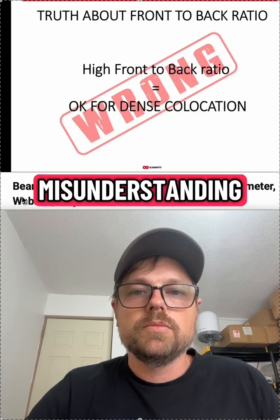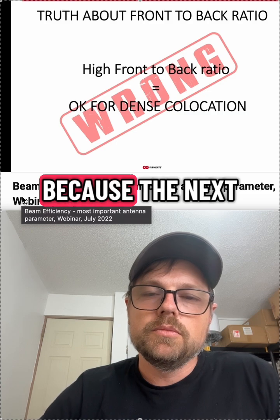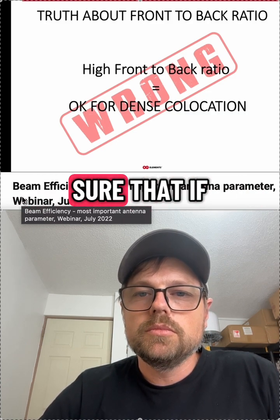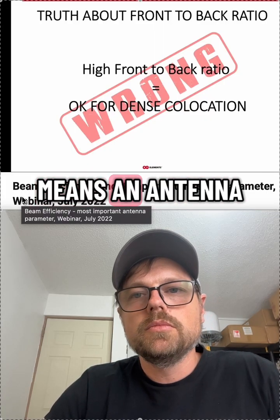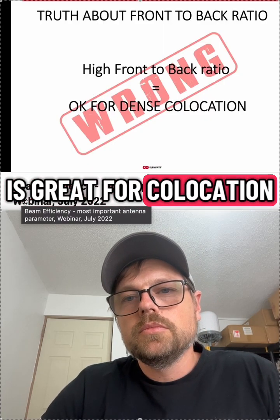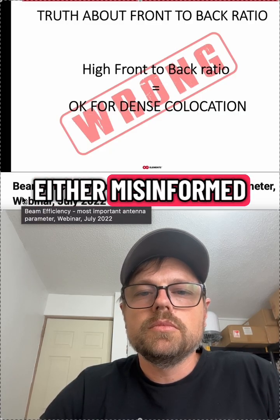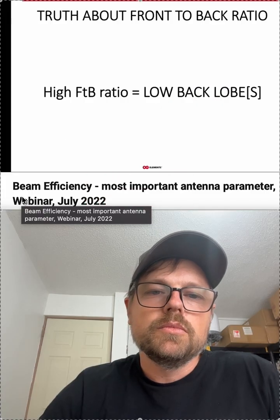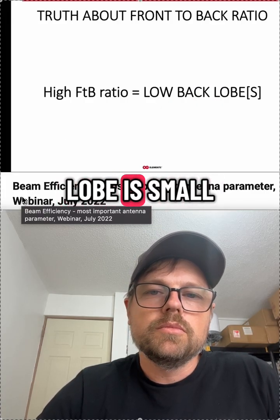It's simply a misunderstanding. It's important to really get this right, because the next time you have a conversation about front to back ratio, you can be sure that if anyone is saying that high front to back ratio means an antenna is great for collocation, you know that the person is either misinformed, or simply didn't go deep enough with the topic. High front-to-back ratio means that the back lobe is small.